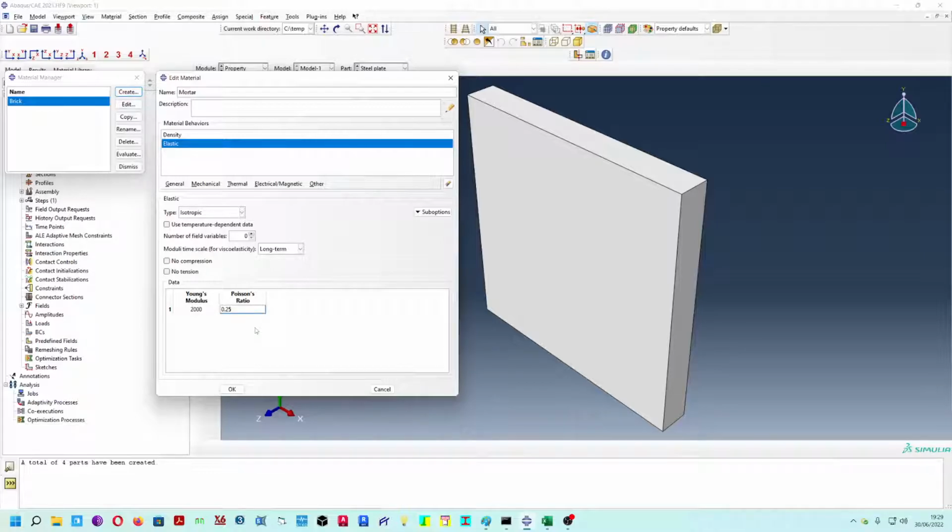which moves along the hydrostatic axis of the criterion we are choosing for the mortar. That's the reason why you can perform an elastic analysis for the mortar instead of a plastic one. Of course, you have to check displacements, forces, and tensions on the mortar to avoid non-convergence results at the interface between bricks and mortar.